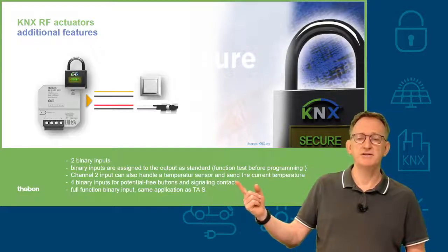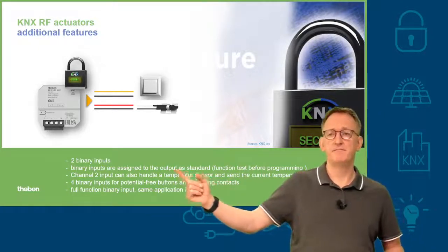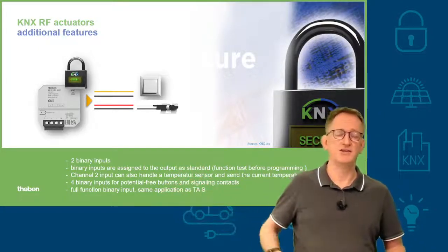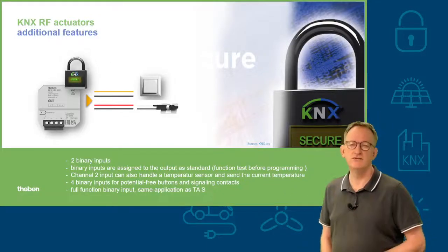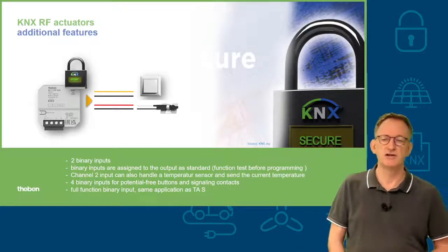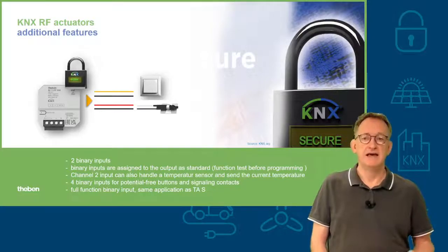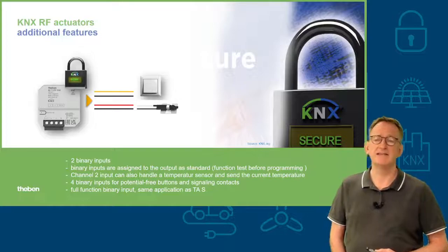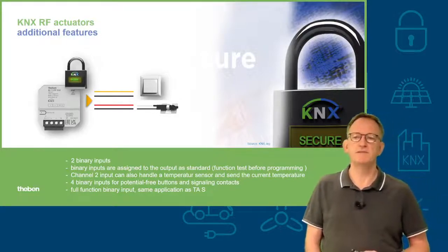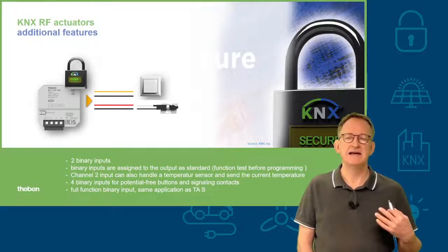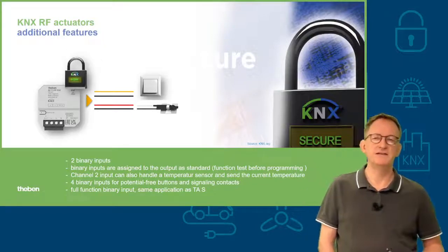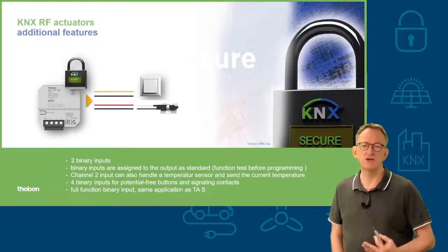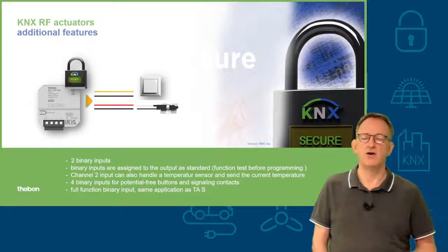Very important, both channels are potential free, so please do not set any potential to these inputs. Also, if you are using the devices at the beginning in an unprogrammed way, the channels are configured so that they control standard functions of the device.